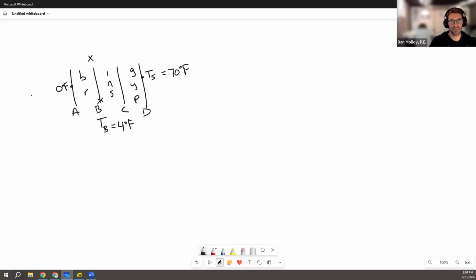So if you calculated that it was 66 degrees, you have to ask yourself, does that make sense, seeing as that's on the other side of the insulation? It's warm inside, cold outside. The brick is not a great insulator. The gypsum board is better, but it's not as thick. Neither one of them has really excellent insulating properties. So they're more or less going to have similar temperature on either side of those layers. So if this is 0, there's no way this is going to be 66. This could be 66. This is more likely to be much closer to 0.